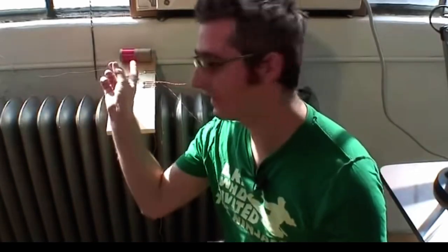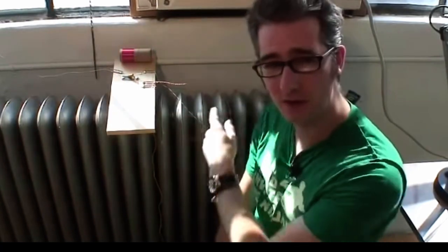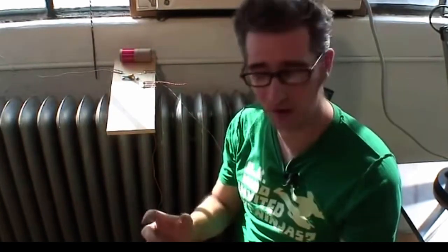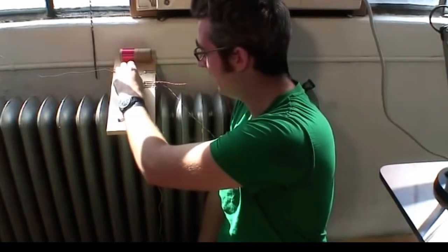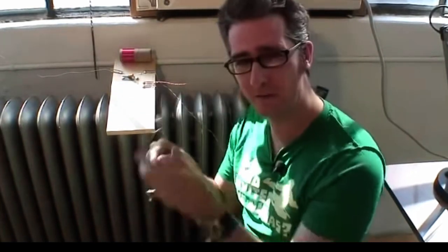Alright, now I'm by the window, and I'm doing that because I've got the antenna going out the window and the ground hooked up to the radiator here as a ground. And what I've done is I've taken the little cat whisker and I've adjusted that, and now through the earphone I can hear radio. It's like a talk radio show. I can just faintly hear it, but it's enough to understand it.